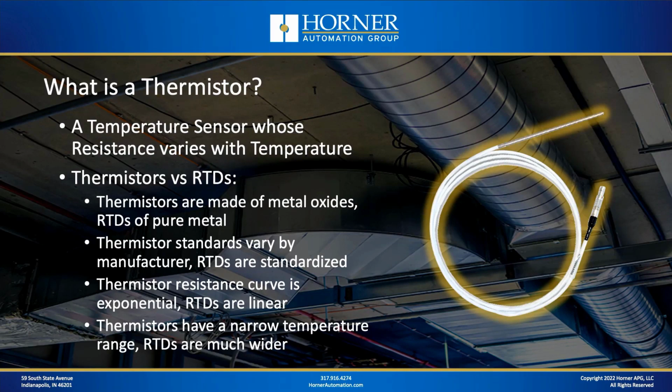Thermistor standards vary by manufacturer, whereas RTDs are more standardized. So if you buy a PT100 RTD from a manufacturer, you can pretty much know that the same PT100 specification purchased from a different manufacturer is going to yield about the same results. That's not always true with thermistors.